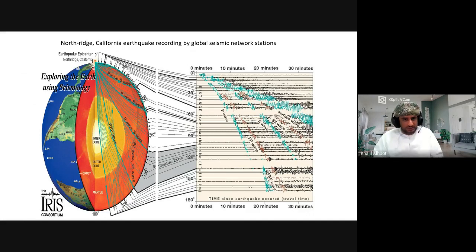As I said, for earthquake seismology, I keep recording. Why do I keep recording? Because I never know when an earthquake happens, so I need to record it. Whereas for seismic exploration, I have the control. I have the hammer, or I can determine when to make an explosion of dynamite or when to start vibrating with the vibroseis or vibrator. So I have control over time. I start recording after I hit the ground.